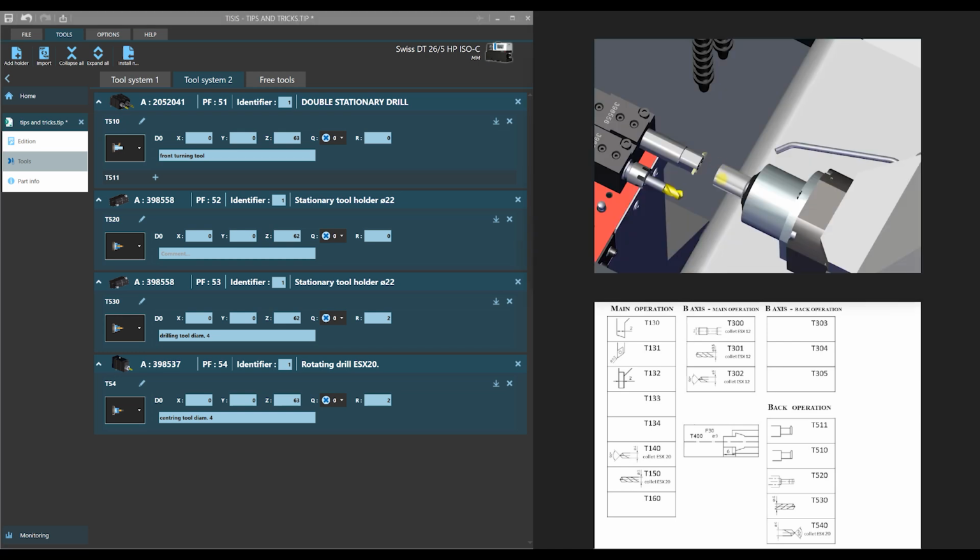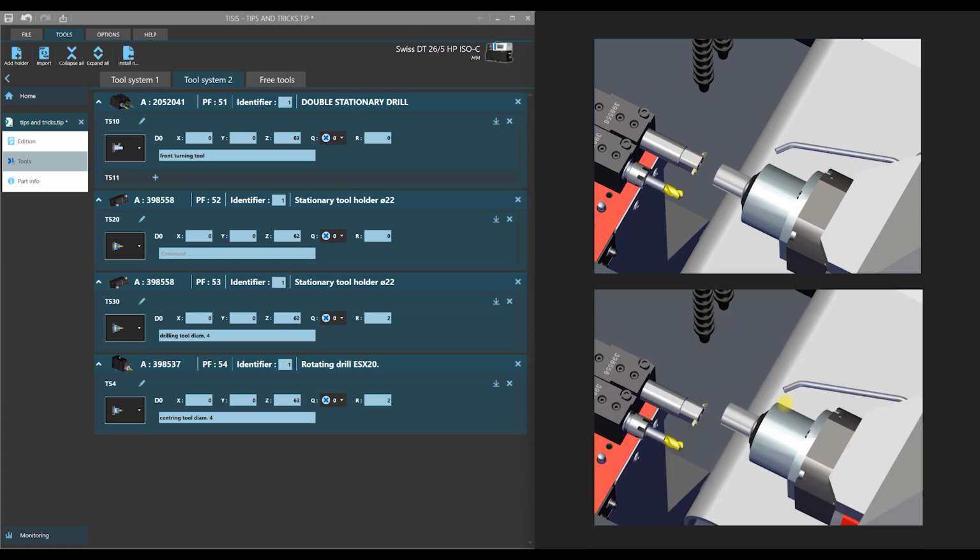In this drawing, you see the situation where the center of a part in back spindle is in a line with the center of a holder. And please look at the drawing in the bottom. Here you see that to have center of a part in a line with this tip of a tool, it is necessary for back spindle to move in this direction, but this is direction in minus in axis x4. That is why we should enter here as geometry minus 30.